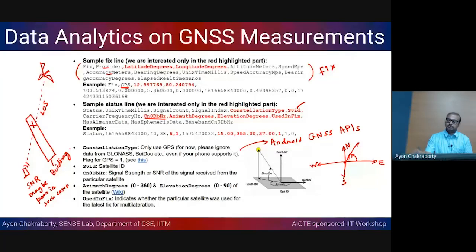And you can think of 3D, because you can also have the top side: if you take a 90-degree angle vertical from that plane, that is the zenith, 90 degrees. So you can also calculate your elevation, that is, how much you need to raise your head in order to view the satellite. The satellite is in a particular direction, given by the azimuth, because if you look towards the northeast, you will be able to see the satellite.